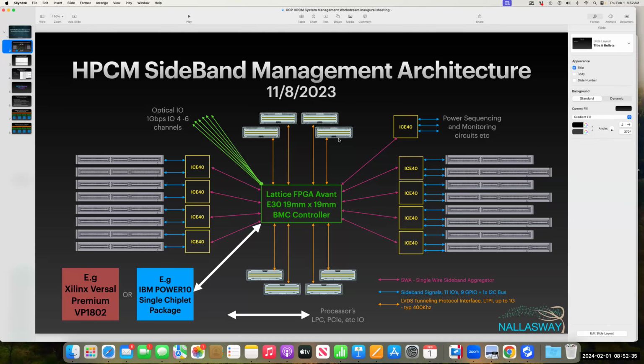Obviously we know that with Ethernet you don't have any sidebands at all on cables, whereas with PCIe you have all of the sidebands carried along, right? So what we wanted to do there was simplify this to our own, because it's just between these modules. We would maybe use LTPI or some variant of LTPI to get the sideband, out-of-band communication between the modules up and running.